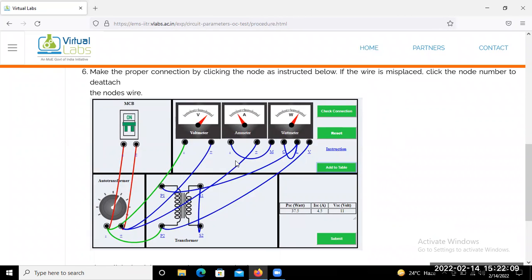Okay, so I already mentioned a few minutes earlier that for all the instruments, we connect during the short circuit test on the LV winding and short the HV winding. So this one is considered the HV winding. You are in P2. This one is the LV winding. So this LV winding is shorted. Okay, and the connection diagram is the same. Instead of open circuit, power is given to this auto transformer from here to here, and for measurement purposes one voltmeter is connected. This voltmeter is connected in parallel with the auto transformer, and one ammeter you require to connect.